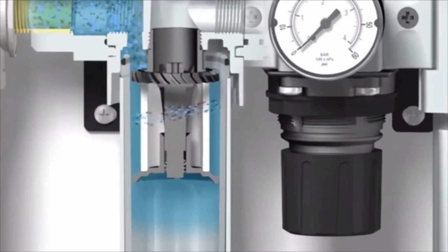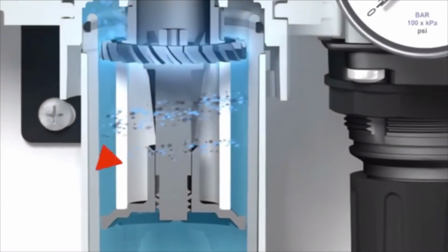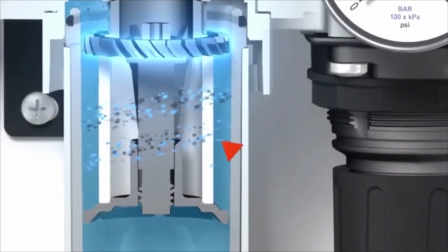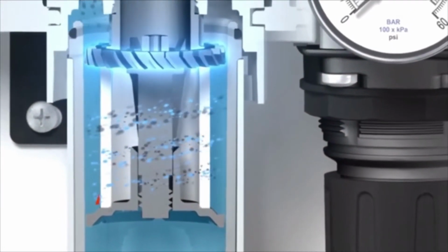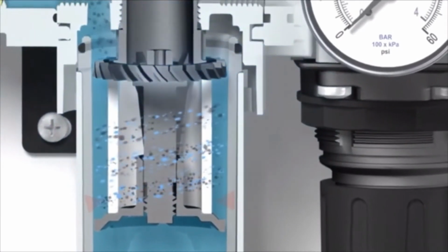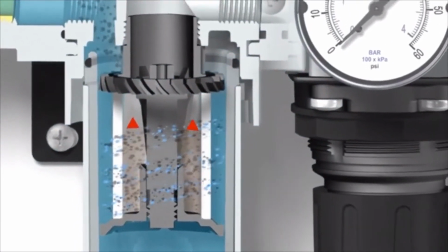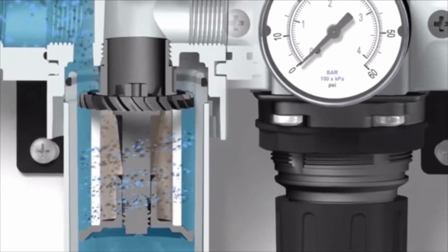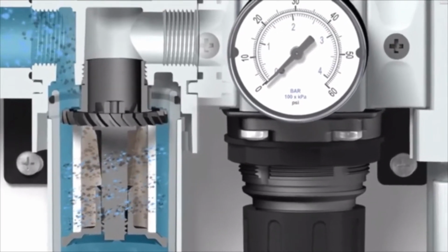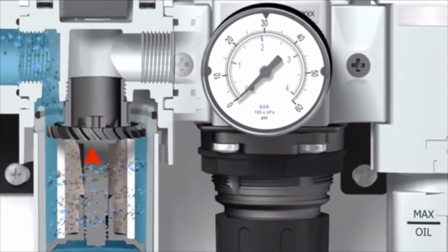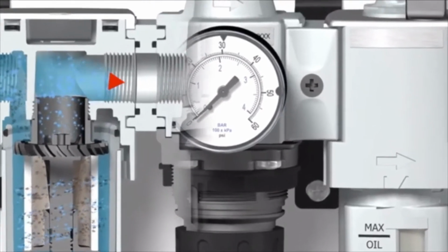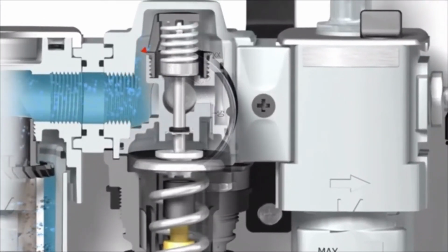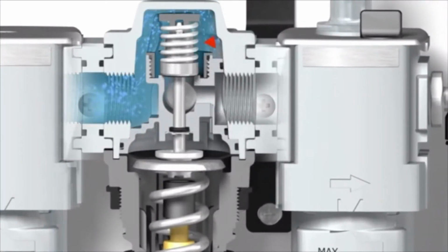Just like in the bulk liquid separator, a series of vanes or louvers in the filter circulates the air in the first stage. In the second stage, the air passes through a screen of sorts, called an element, in order to catch unwanted debris. Once dried and cleaned, it is common to adjust the level of air pressure coming out of the compressor. This adjustment has an impact on how much force the system generates.